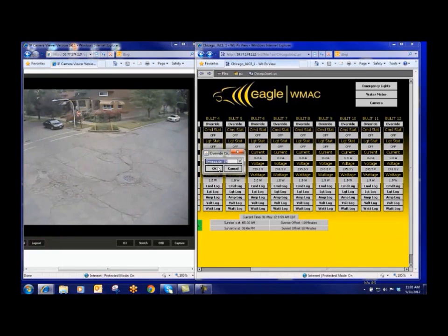We want to override the light on. So when I click OK, if you'll watch the light, you'll start seeing it come on. At the same time, if you'll watch the command status, it will immediately turn green, but light status will not change until we start reading current. You'll see an inrush of wattage as the ballast fires the bulb and everything levels off. You'll see it drop down to around 170 combined watts between the two lights, which is a 90 watt and a 60 watt, with the ballast equals roughly 170.